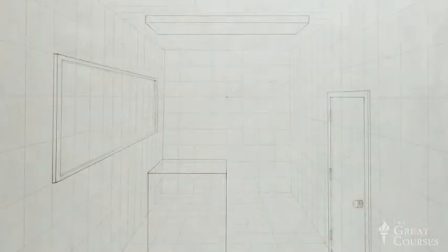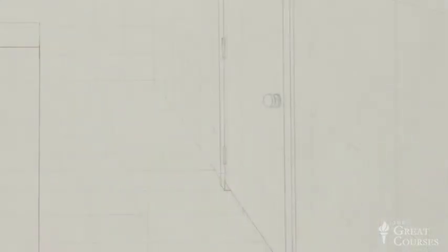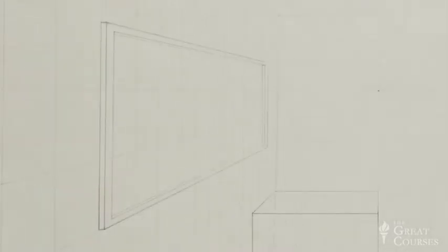Note in this drawing how the door, the corkboard, and the light fixture have been given thickness and dimension and projected into the space of the room. The door has a volumetric doorknob, and volumetric hinges too, built out of little cylinders. The corkboard has both internal and external planes. You'll also note that the objects stand out from the construction lines. That's because they're handled with a stronger line weight.